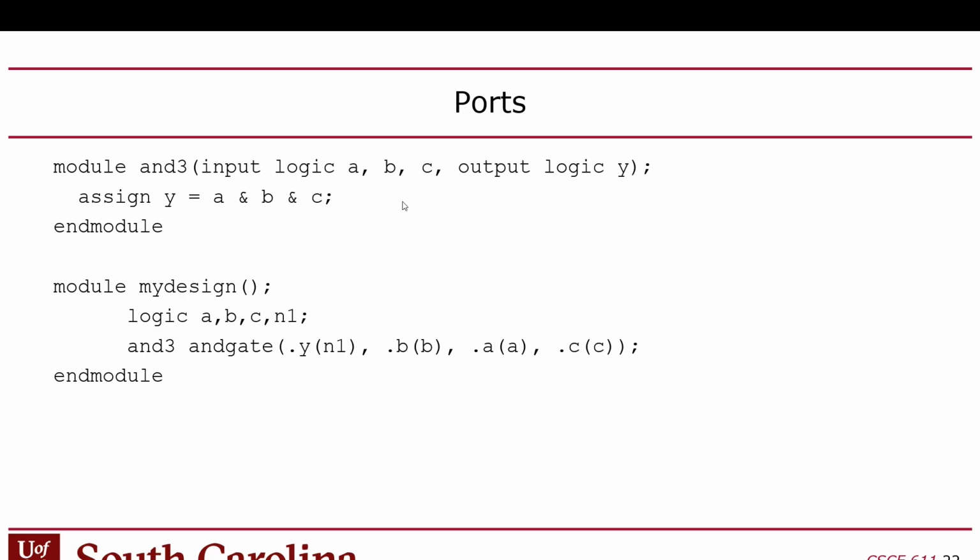This creates a problem when you go to debug designs on hardware, because when this gets synthesized into the physical design that goes on the FPGA, into the database file which is called a bit stream, it only retains one of those names, and you don't know which one it retains. So when you go looking for signals inside of a synthesized design, you don't know what to look for.